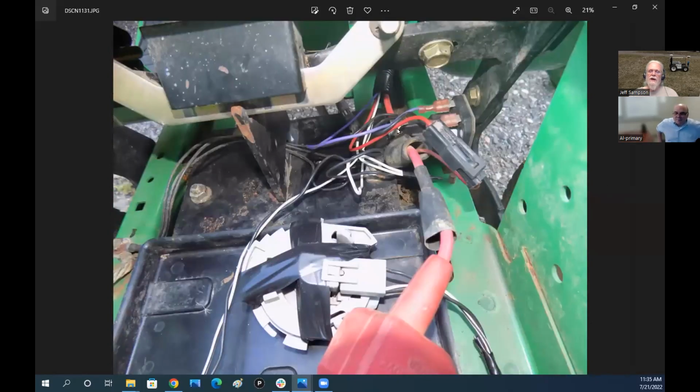So in the back, originally, here's my 5 wires. There's the big wire for the starter, bolted right to the starter solenoid here. And there's 2 white wires and a red wire and a purple wire. The purple wire just plugs into the solenoid to turn it on and off. And the red wire actually had a connector, so I could just disconnect that one. That's just supplies 12 volts to everything in the front.